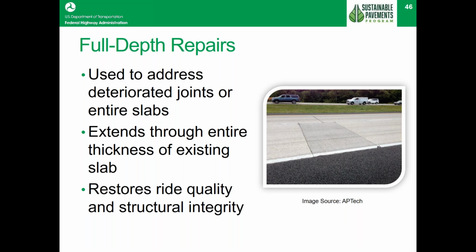Similar to the partial depth repairs, we talk about full depth repairs, very similar, okay, but it's usually a larger repair. Sometimes this will involve replacing all the way down to the base. Sometimes it involves replacing or installing some rebar steel and/or some dowel bars that get drilled into the existing pavements. Often this kind of work is done on interstate highways where closing the roadway for a long period of time would be difficult to do.